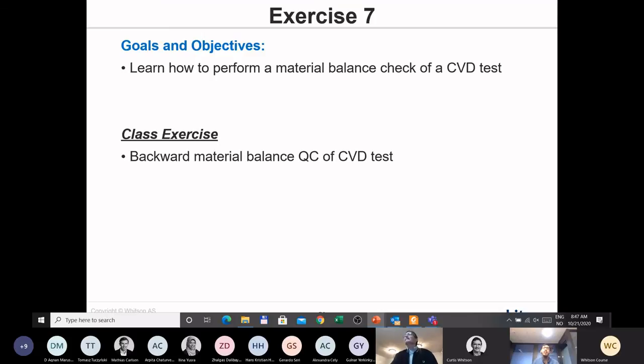What I was trying to say is that if you collect different samples in the field, and the total composition that you have measured for those samples varies a lot from one sample to another, let's say one sample is a lean gas condensate, the other is a black oil, and you have a very large number of samples going from lean gas condensate to black oil.